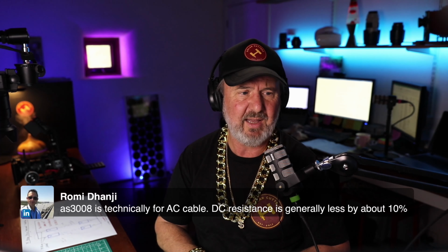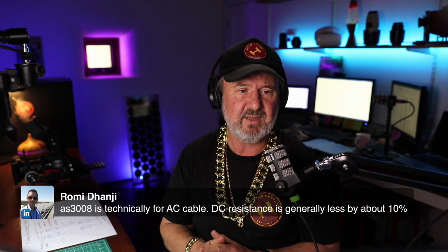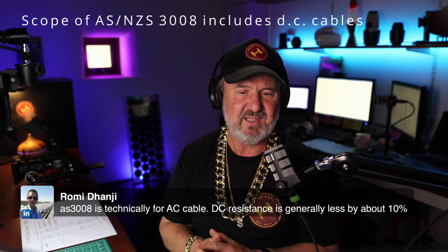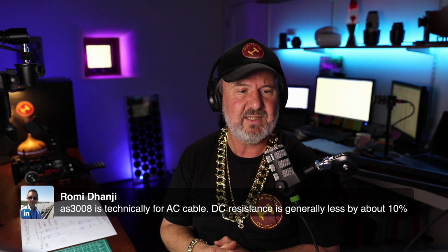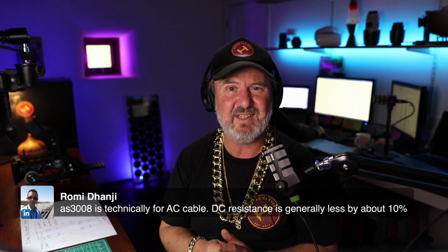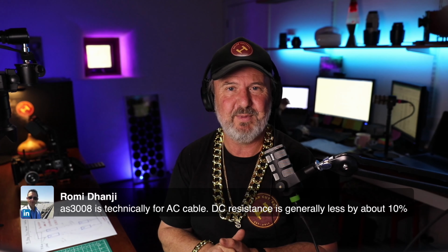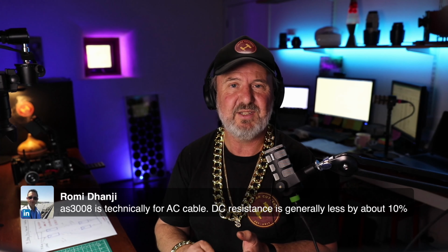Okay, so yes, good point, Romy. AS 3008 is technically for AC cables. You're dead right that the DC resistance is a little bit less. I don't know if 10%, it might be a little bit on the high side, but it is less for PV or DC cables. And the reason for that is that DC doesn't suffer from any of the effects such as proximity effect of AC and skin effect of AC.